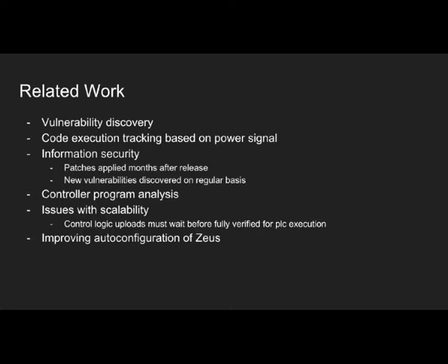The other thing is alternatives. Instead of doing contactless, you could do power signal analysis. But the problem with power signal analysis is that you're physically connecting something to the PLC, and you're drawing power from the PLC itself. So you could potentially be affecting the real-time performance that the PLC has. Whereas when you're doing contactless, you don't have any overhead at all. And this is very important in information security because patches take a long time to apply.